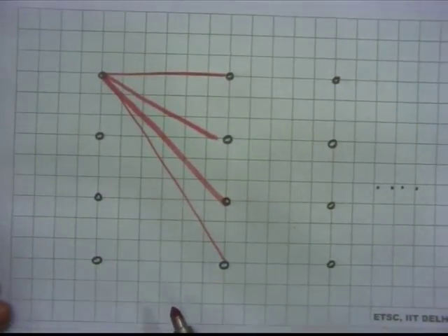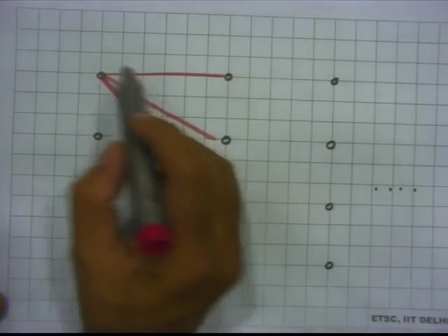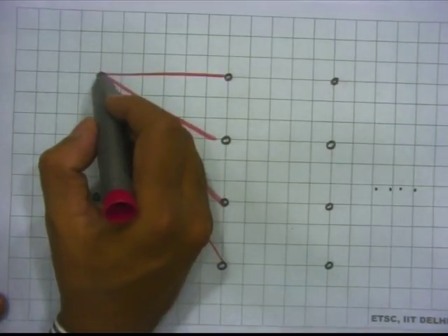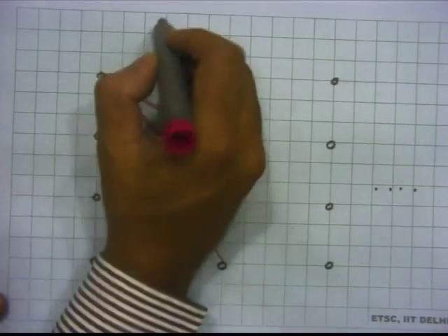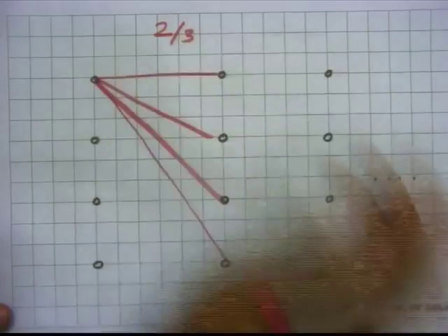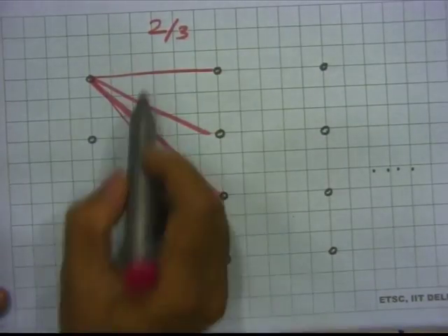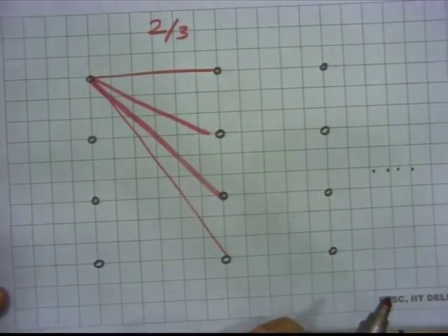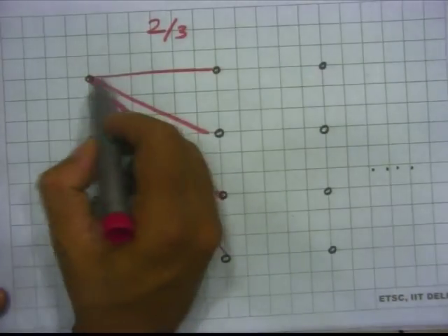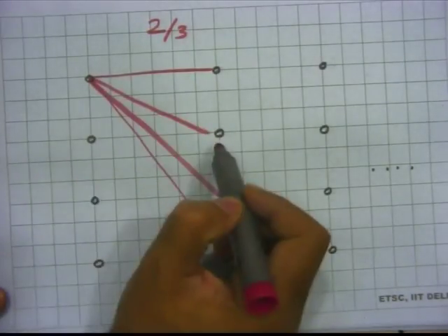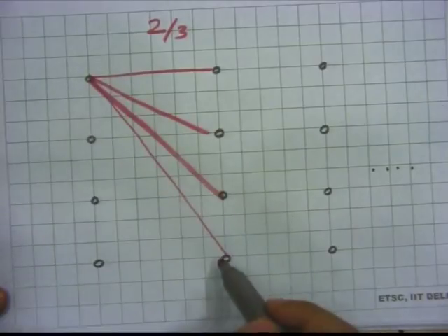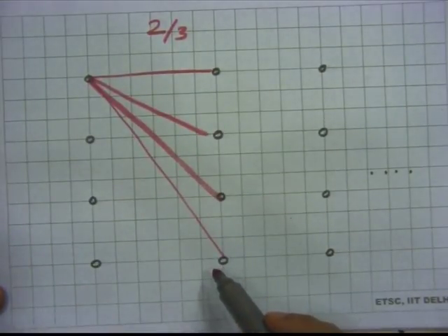and so on and so forth. Now, for any bit that comes in, and this is a rate 2 by 3. So, 2 bits come out. So, there are 4 possible transitions. Okay, 0 0 comes in, take this branch, 0 1 take this one, 1 0 take this branch, 1 1 take the last branch. What happens?